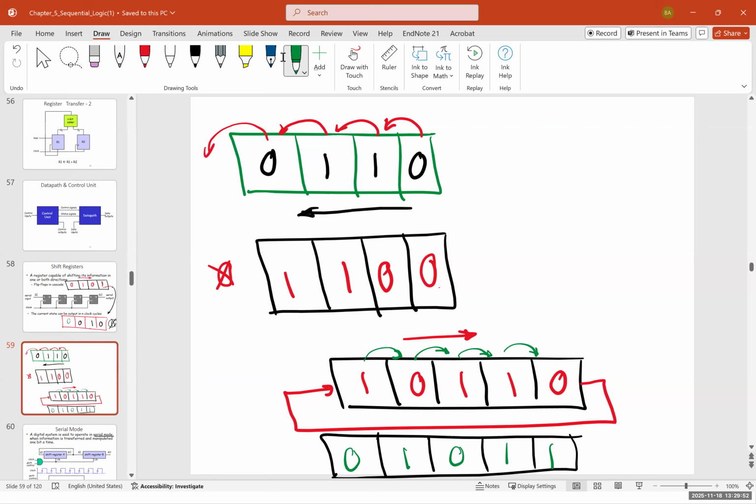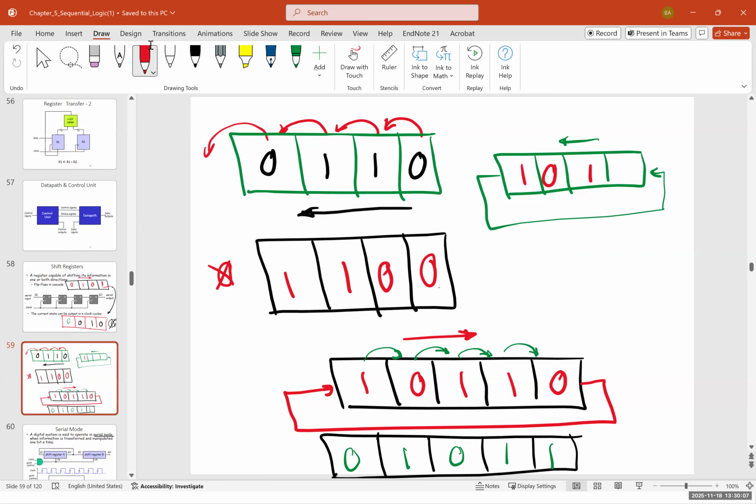And I can do the opposite as well. We may have a system with a shift to the right, but that one was to the left. So again, this goes back here. Imagine this is a 4-bit system. If this is 1, 0, 1, 1, and I shift everything 1 bit to the left, then we would have 0, 1, 1, 1 as the answer.